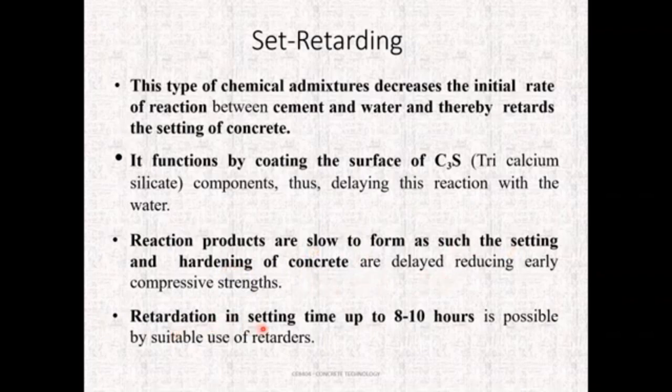Retarders can delay setting by 8 to 10 hours. Usually, when we are using ready-mix concrete, it will take a lot of time to move it to site. So, in such cases, the workability and the properties of the concrete can be affected.